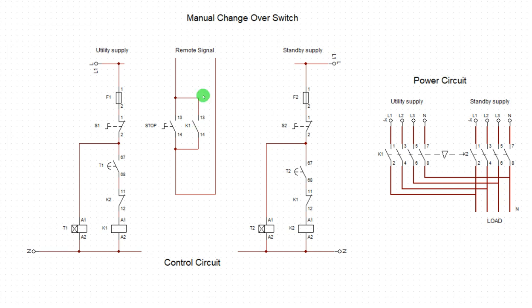That cable is the signal that comes to this area. So from your panel, you run a cable to your genset. But before you terminate that cable to genset, these two should connect to a male plug. Meanwhile, the one coming from your genset will connect to female plug. So these two will now join together by the genset. So when you want to take the gen to another location for service, you now detach that cable. When you come back, you marry them together. Once you marry them together, that transmission cable will be connected. I hope it's clear. If you don't get it, push in your question.